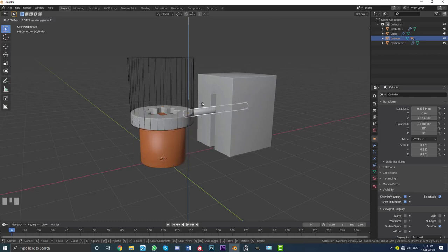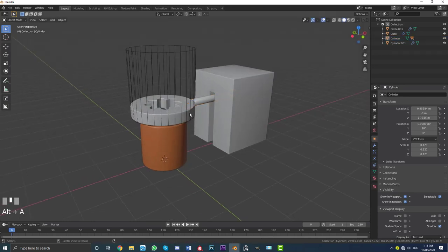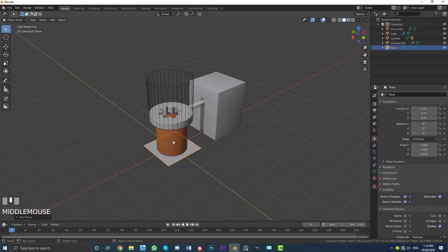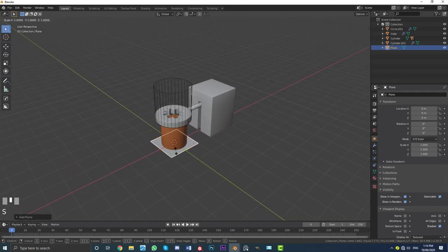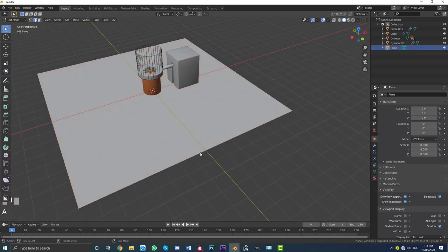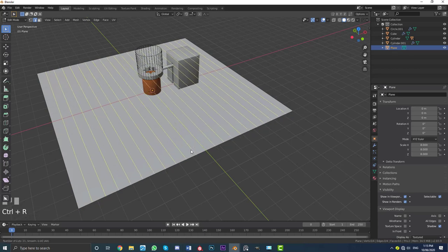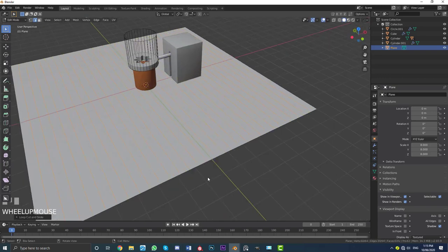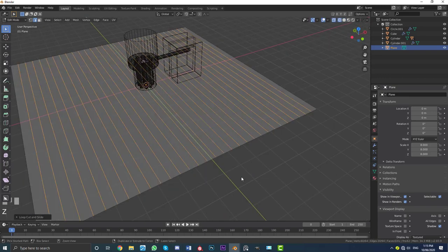We're going to be animating that. So first of all, go Shift A, add in a plane. With this plane selected, we're going to go S8 to scale it up 8 times. Tab into edit mode, make sure you're in edge select, Control R hovering over here, and then roll in some loop cuts. It can be as many as you want. I'm going to do about this many, click them in.